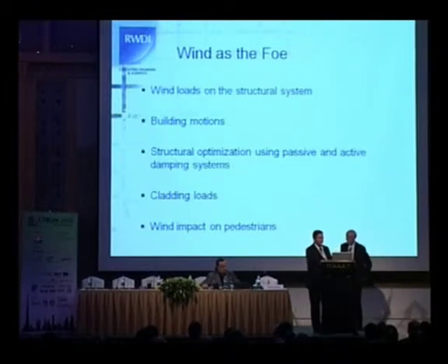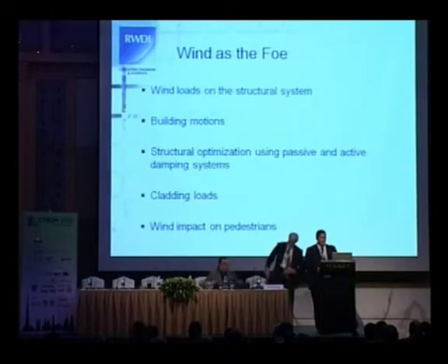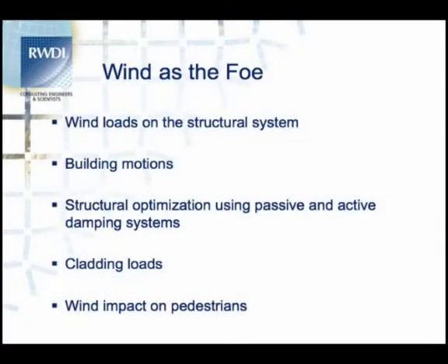Well, if we think about wind as the foe, it's mean, it's nasty, it causes us all sorts of problems. Structural loads sometimes are excessive, causing problems for foundations. There's problems with excessive building motions in some cases, causing discomfort to occupants of tall buildings, which has to be sorted out. There's some optimization of structures that has to take place very early on in design, and you need the input from wind tunnels to do that properly. It's an iterative process, it takes time.